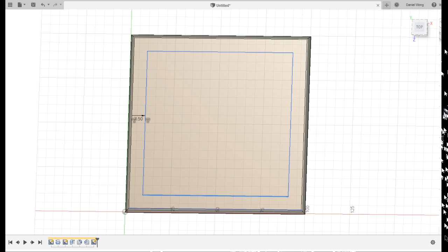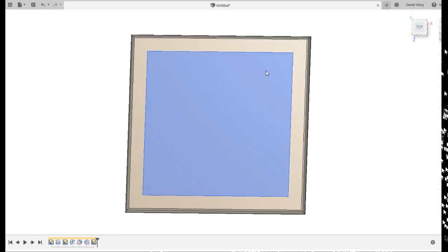Now it shouldn't need you to put any other dimensions in there, because that's already technically defined on that offset there. So you don't need to worry too much about it if it's blue. It's mainly the first sketch of any new geometry that needs to be the case, but when we're offsetting it, it doesn't. Anyways, we're going to stop the sketch there.